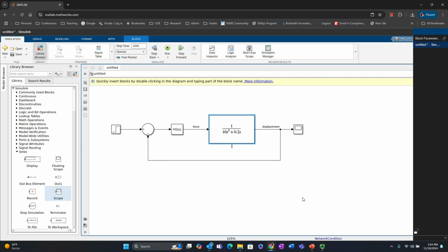a mechanical system with inertia J and viscous damping B, free to rotate. So the displacement here is angular displacement, at least in the context of the problem we are looking at. And because I am recording this for a homework that we are designing, the focus is on angular displacement. And to be able to achieve angular displacement, we'll be applying torque to the system, and torque goes in and angular displacement goes out.